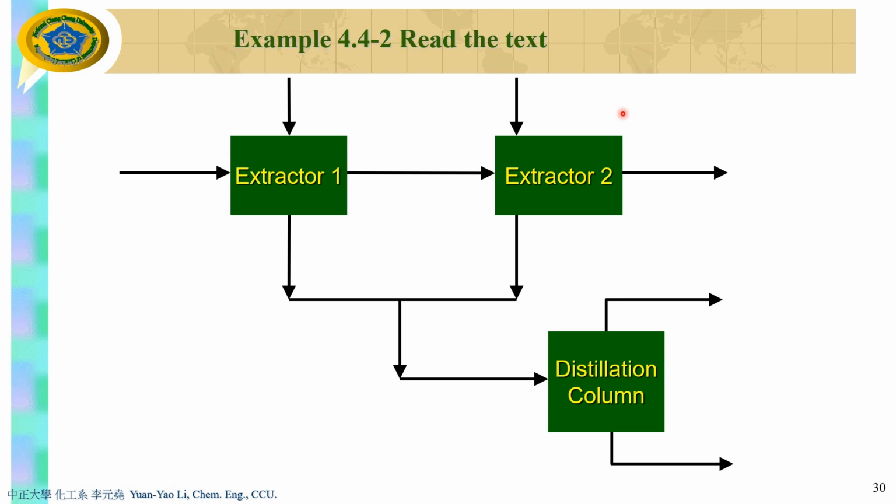The mixture passes into a settling tank, where the phases separate and are separately withdrawn. The phase rich in the dilute component is referred to as the raffinate. I already showed you this, right? And the phase enriched in solvent MIBK is the extract. The mixer settler combined is the first stage of this separation process.